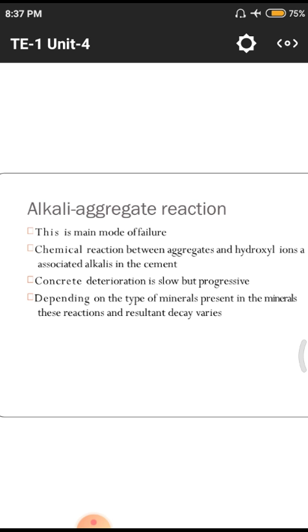Why? Because in some cases they are using different quantities of water with salt content. Due to the salt content also it leads to alkali aggregate reactions. In the initial stages of the construction it gives good strength. After 1 or 2 years are over, automatically some rusting will take place and cracks will be observed. Small particles will break. That is due to these alkali aggregate reactions.